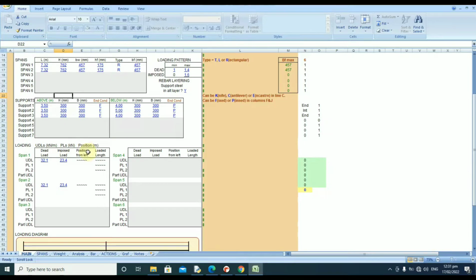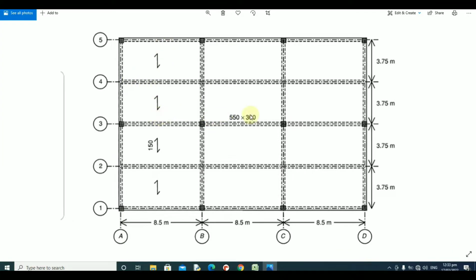This is a structural plan, and we can see the columns here and the lines, the thick lines are the beams, and these square boxes are the columns. And we can see the slab panels. The slab panels are the kind of empty spaces between the beams, and then we can see the symbol which tells us that the slab is a one-way slab.